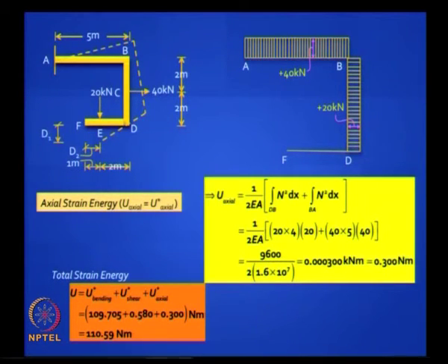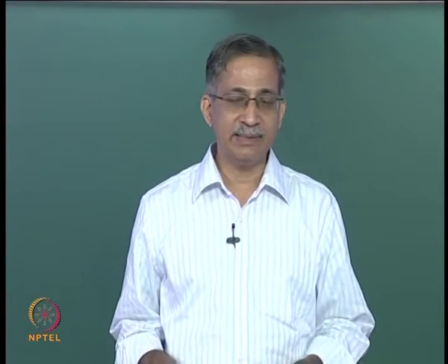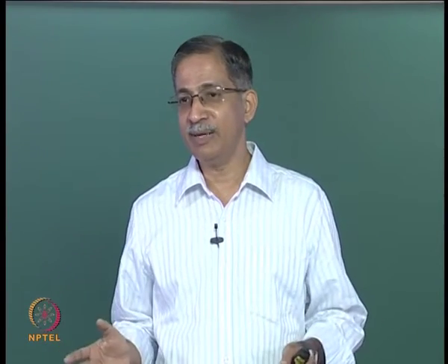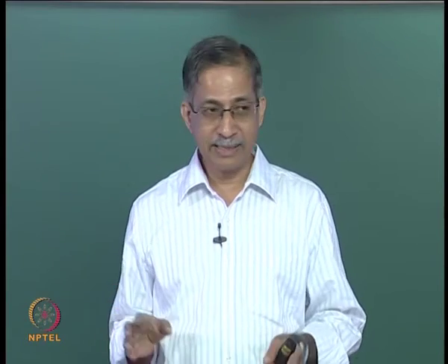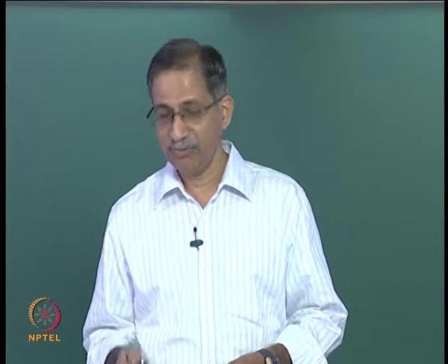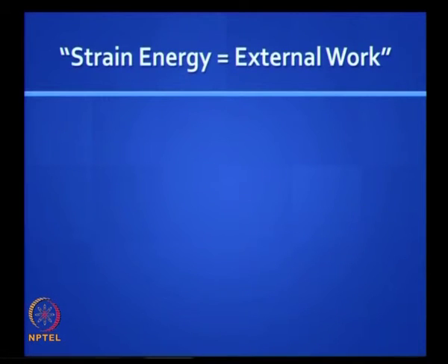It is like assuming that the shear rigidity is infinite and the axial rigidity is infinite, and that is the reason why this assumption that we frequently make in structural analysis when we deal with frames is justified. But there are exceptions, and if you want to be accurate you can include those effects as well. In matrix methods we will do problems where we can do this more exactly.